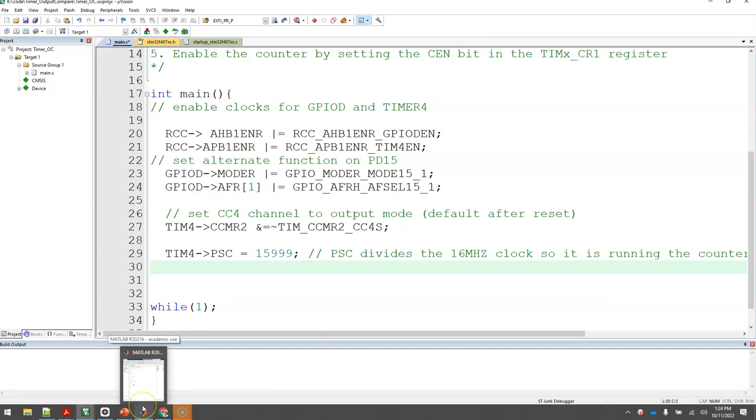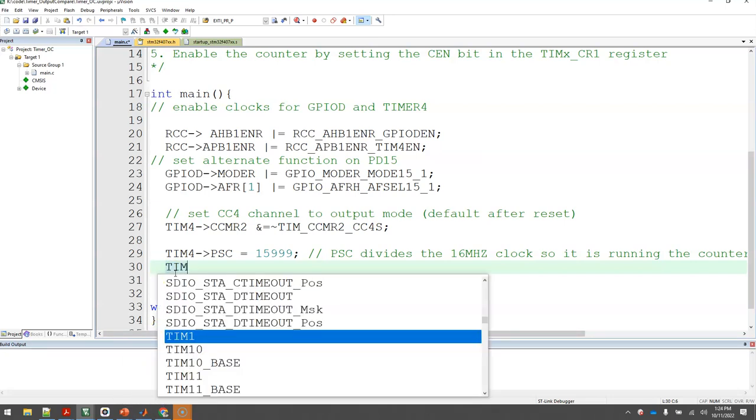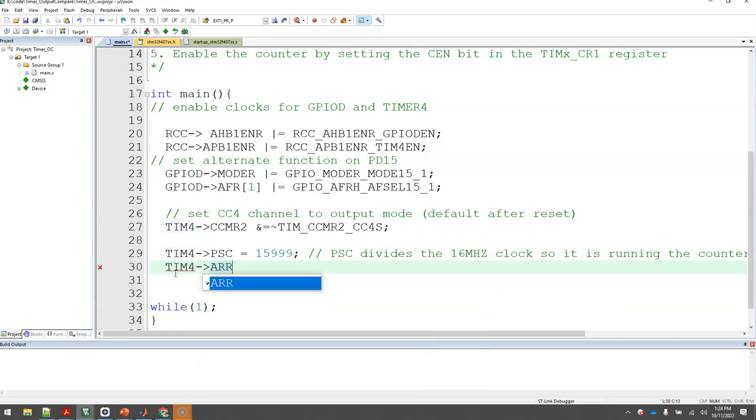Right? 1 kilohertz. If I want my thing to be on for half a second and off for half a second, I want a 2 hertz clock. So that means I want to divide that timer by a total of 500 to generate the clock I need. So let's see, 500. Okay, so what this will do is now it will create a 2 hertz clock for us.